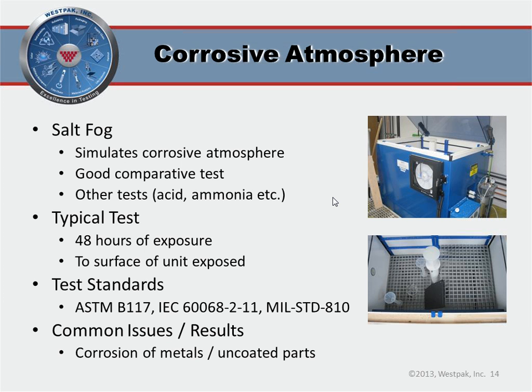As you can imagine, the big thing here is material selection. You have to think about uncoated steel is a big one. When you have PCBs, all of your small components, solder joints, etc., all of that can have corrosion issues. Generally, if you're using stainless steel or anodized aluminum, this isn't an issue, but it's the little things, like hardware, that people forget.